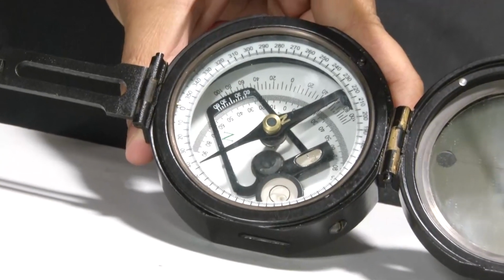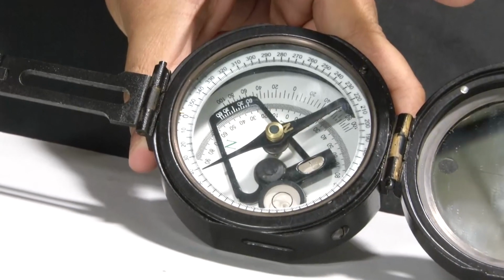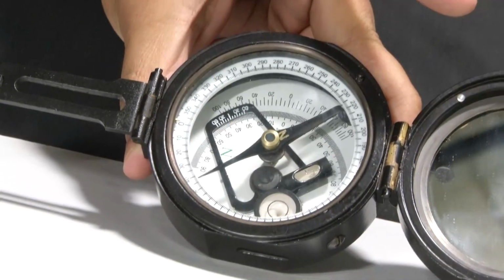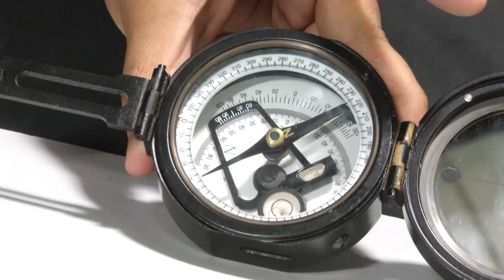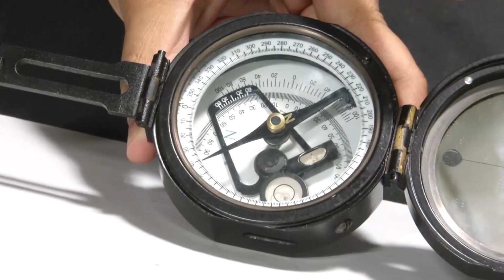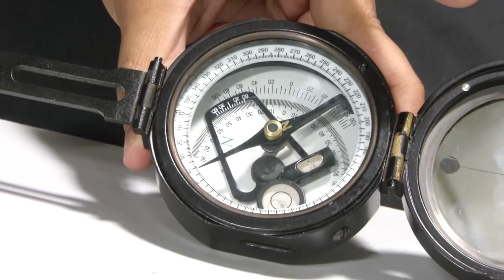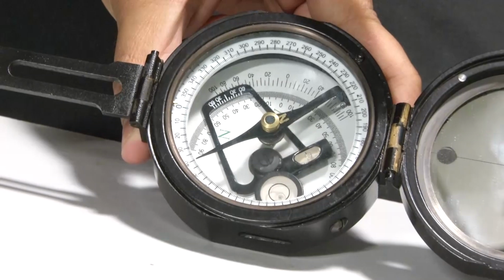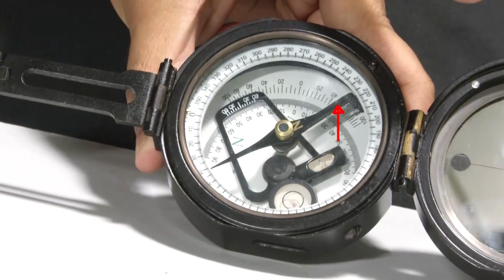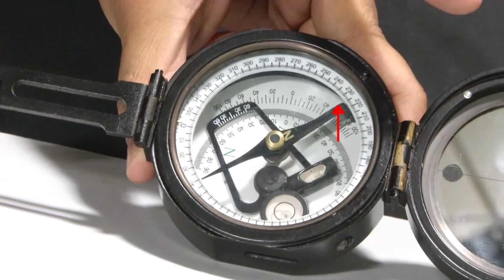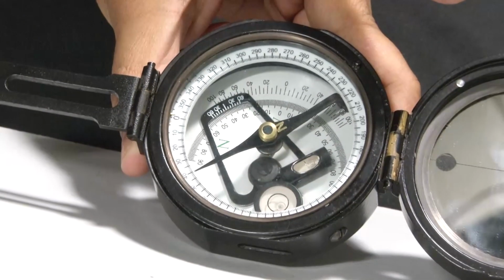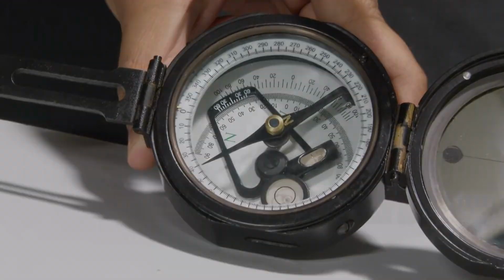In order to note the reading, it has to be carefully kept in mind that we take the reading of the northern end of the magnetic needle, to which it is pointing in the 360-degree graduated scale, when the pointed arm is pointing towards the direction towards which our thumb was pointing. So when everything is ready, the bubble is in the center, and the northern end of the magnetic needle reaches 220 degrees when the pointed arm is pointing towards the direction the thumb was pointing. So the strike in this present case is 220 degrees.